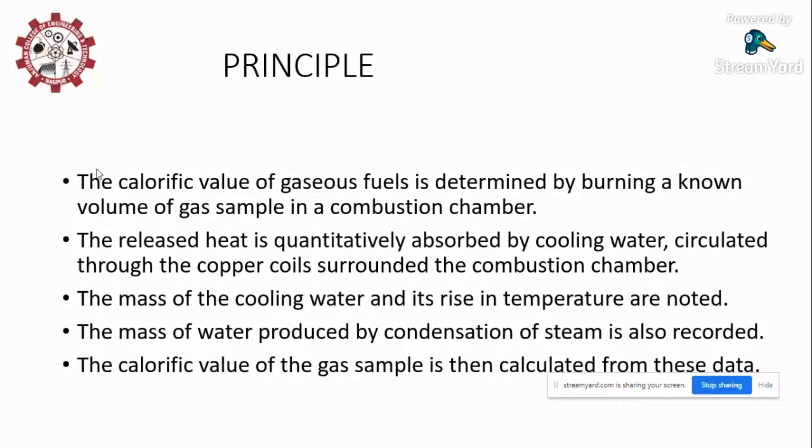We are going to find the temperature of the water then, right? And after combustion, the hydrogen especially produces what? Water. So if hydrogen was there in the fuel, it will get converted into water. The water will be condensed, so we are going to find out the mass of the water which is condensed. From all these data, we are going to find out the calorific value of the fuel.